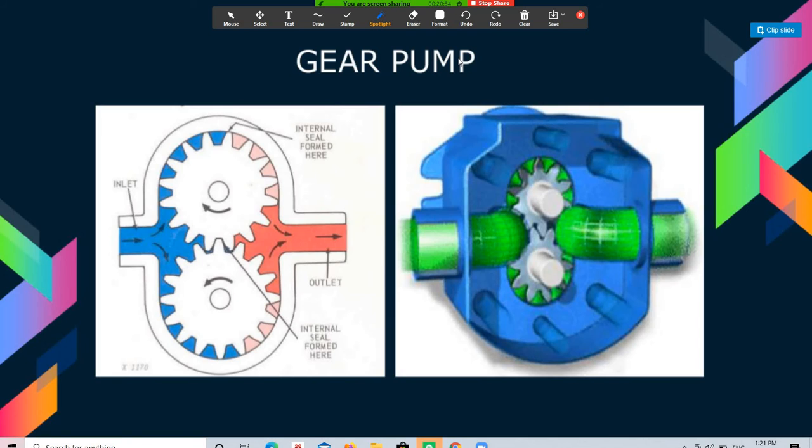The rate of flow is governed by the pressure sensing device of the pump. At present, most Indian tractors are fitted with a gear pump, but the Ford 3600 is an example with an axial piston pump. Okay, now the axial piston pump, in which the pistons travel parallel to the axis of the pump, is called the axial piston pump.